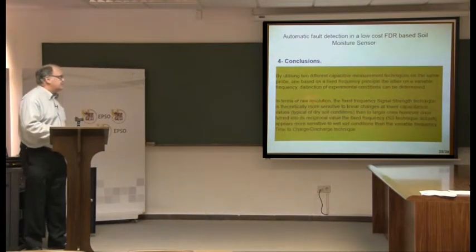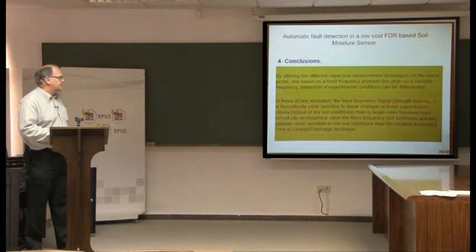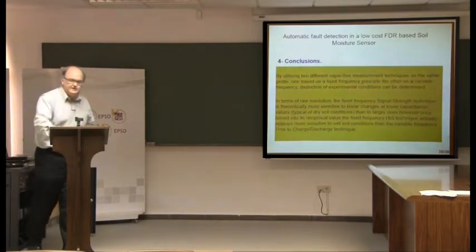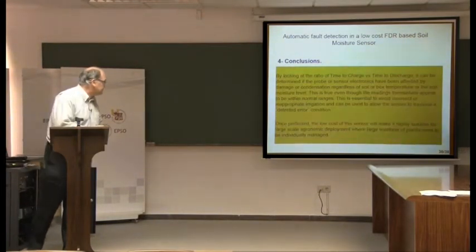In terms of raw resolution, the fixed frequency signal strength technique is theoretically more sensitive to linear changes at lower capacitance values, i.e. dry soil conditions. However, when it's turned into its reciprocal value, what we actually find is that technique appears more sensitive under wet soil conditions, as you saw on the last slide.